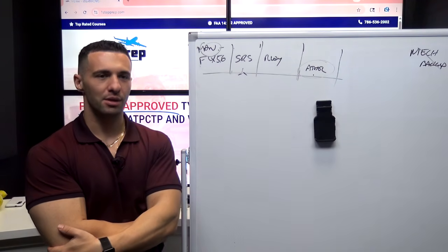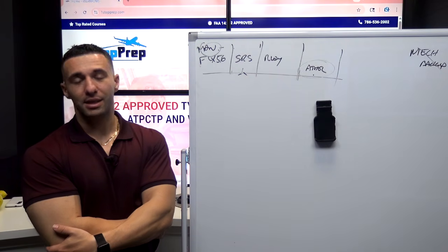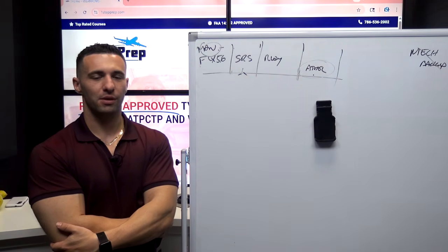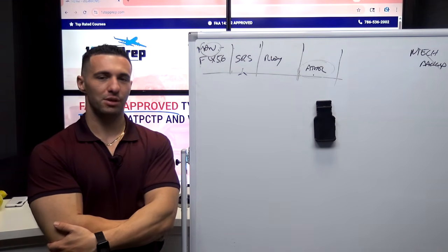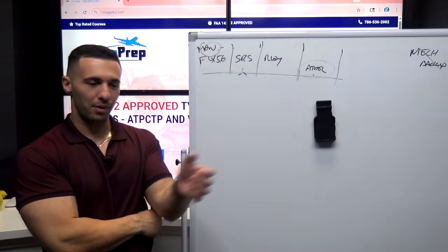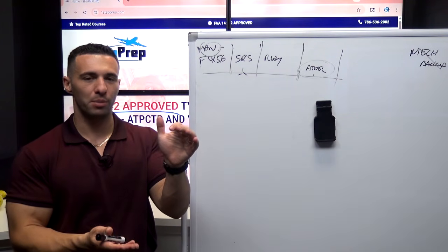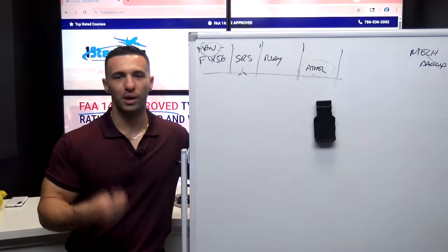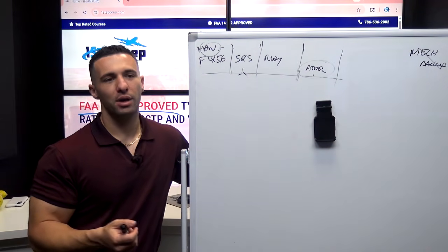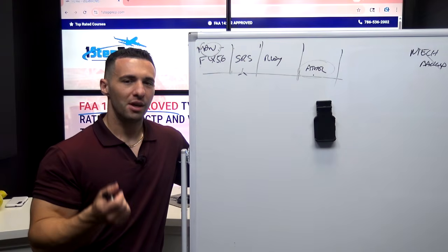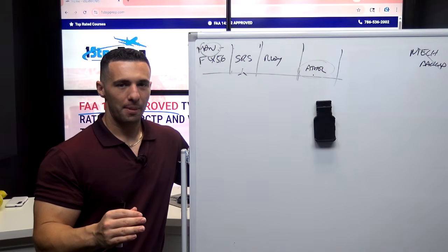You'll have the protection. But you will probably more likely introduce alpha floor, because the configuration that you're in is such that it won't like the energy state given the configuration of the plane, as opposed to if I pull a little bit with flaps 1 versus with flaps 2, it's probably opening up an envelope as far as the alpha floor protection and when it would actually predict that I'm going to need TOGA power. So in my opinion, Rajesh, I try to fly green dot clean.